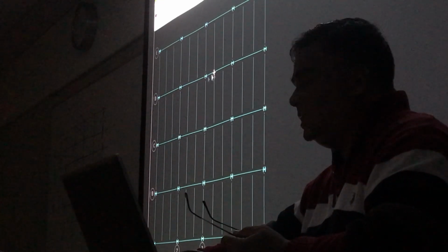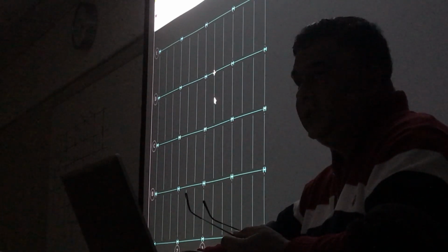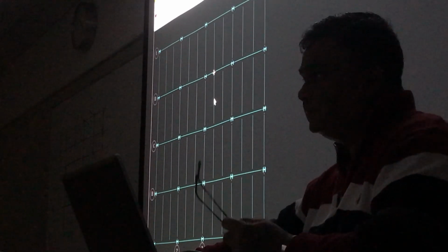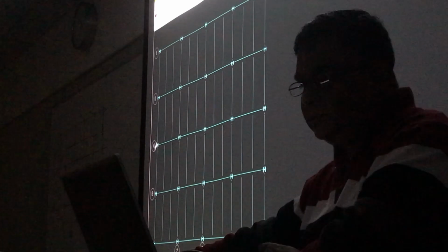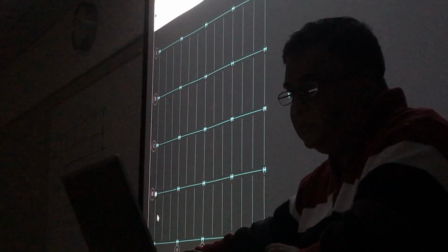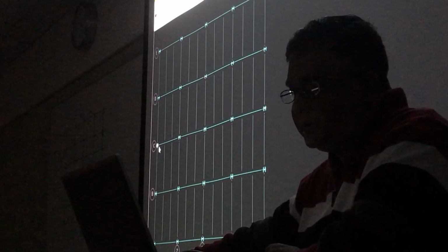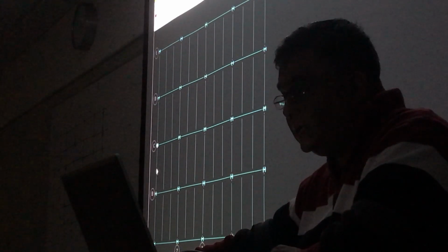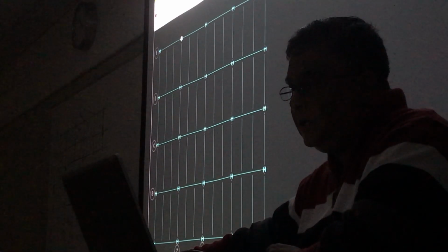That means these beams will be all positive bending moment, and they will be composite beams. So let's change these frames to lateral frames. That means I need to convert that column to take lateral loads, that beam to take lateral loads. How do I do that? I can use layout, columns, and then change properties.